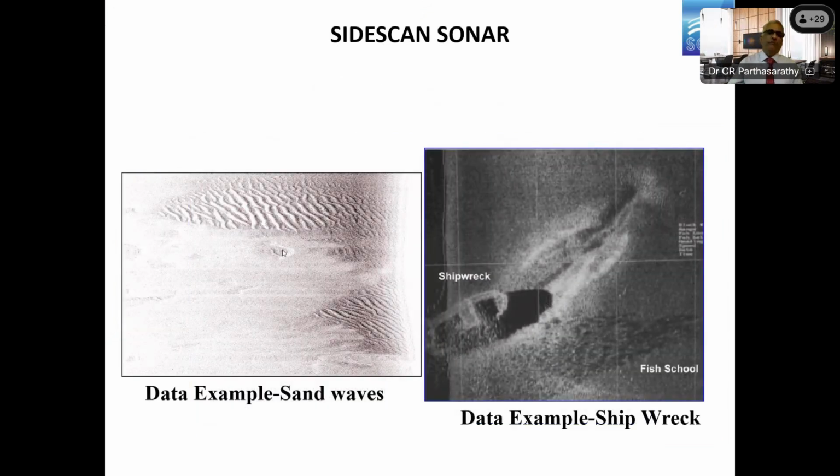If you see these ripples, it's very challenging for the rig to move in to the locations, because you cannot soft pin or bring the spud cans closer to the seabed as the hull is pulled by the tugboat before it positions. If it touches these sand waves, it will actually affect the stability of the rig.